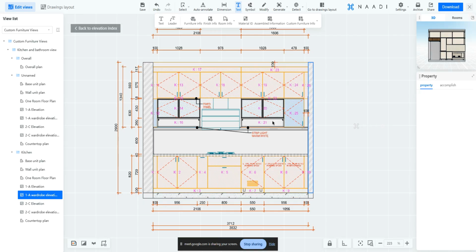In some cases, you might notice some cabinets are getting cut in the middle here, where the boundary is just stopping at the middle of the region. It's not there for the entire floor. In those cases, please don't panic. At the bottom here, you have something called your boundary extent. Just click it and you will see the boundary extent of this elevation.